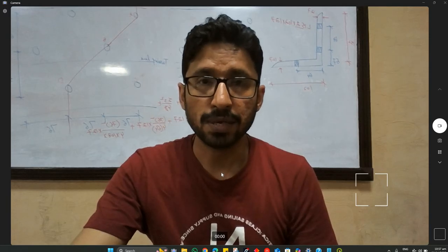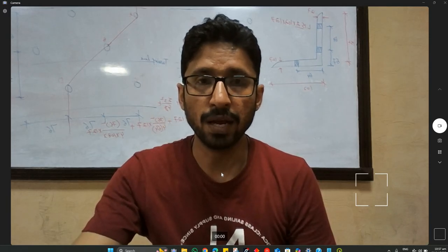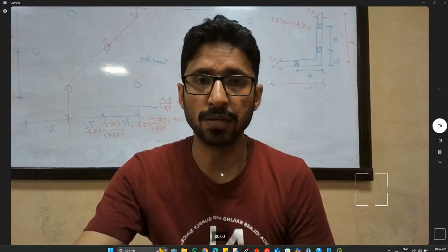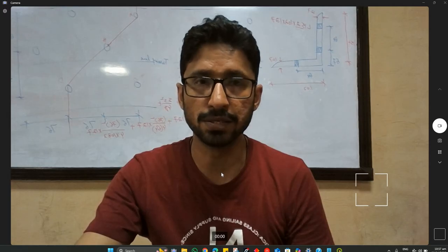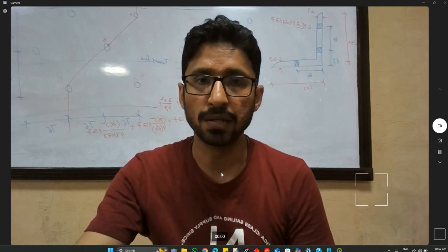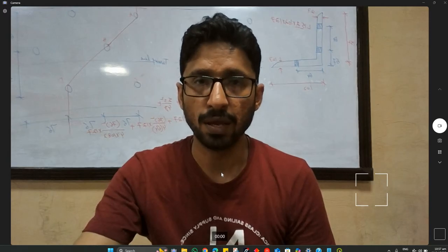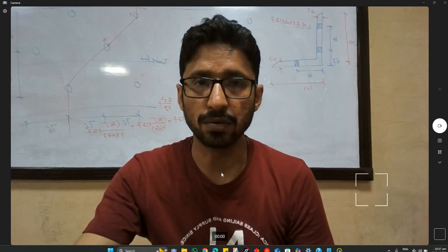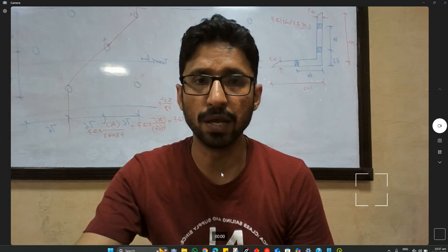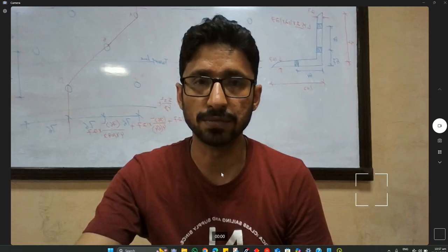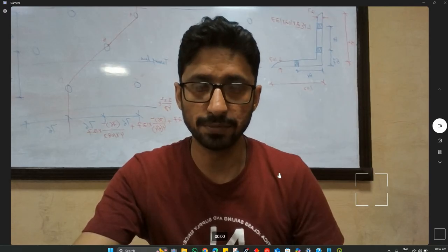And the second one is we will add only the data in the form of points or the lines or the polygons, and add only two fields. The first one is the serial number or the reference number, and the second one is the name of that point or the location. And then after that, we will add the corresponding attributes via Excel format in the form of CSV files. So let's start.